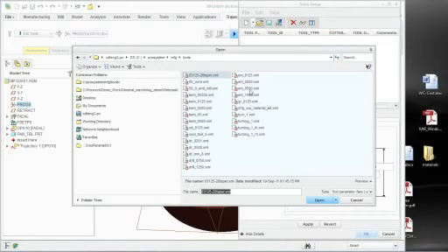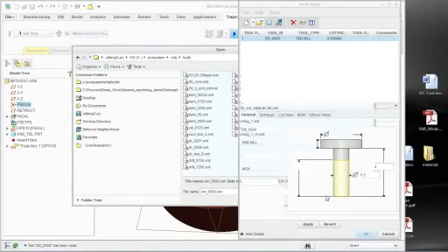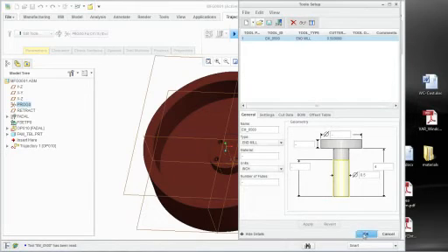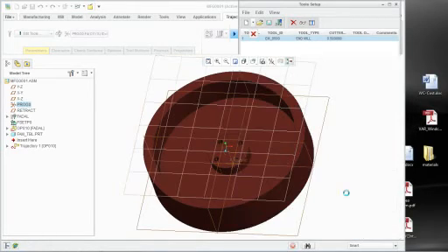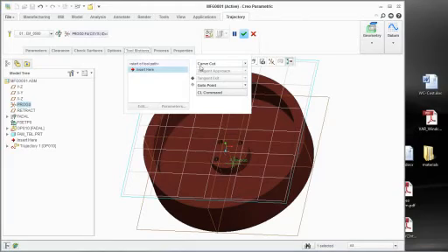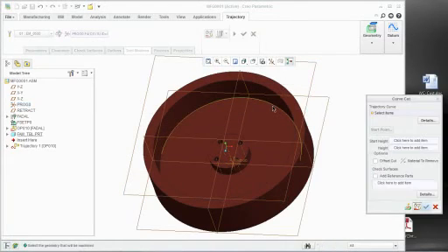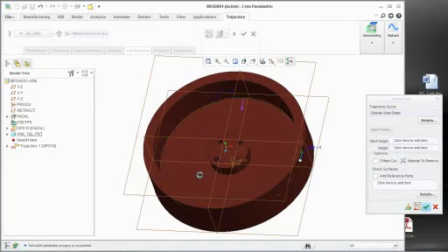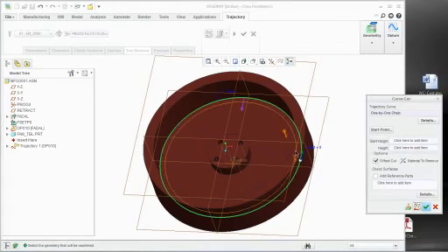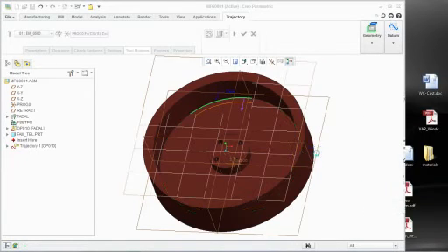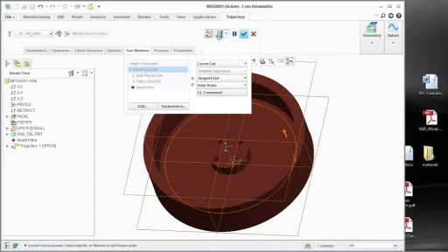We'll use the flat half-inch end mill. There it is. Pick our tool motions that we want. We want to follow this guy and that guy. We do want to offset it. We'll offset it to the inside. So a pretty straightforward little toolpath that I have.